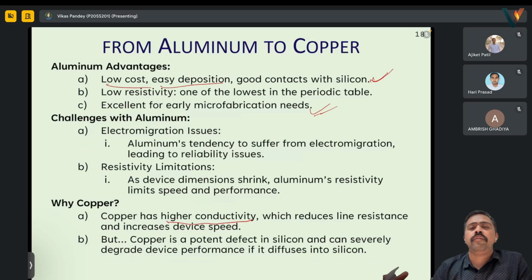We use patterning to form the continuous film into different dimensions. This is very essential, otherwise we have one layer, then another layer, then another layer, with no interaction. This enables different conductance. So in the same layer, some part is conducting, some part is insulating, and we can do that using patterning, with different areas for different functions.